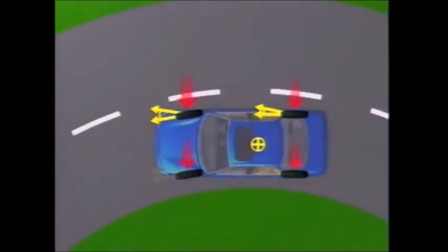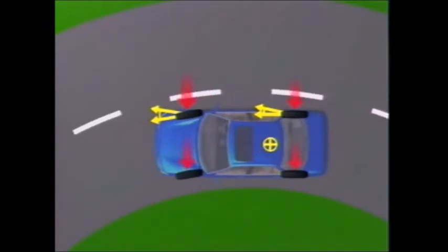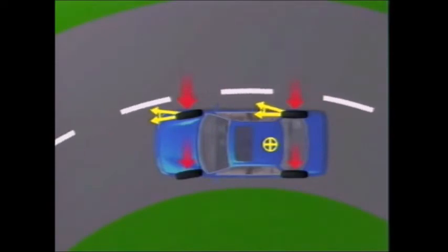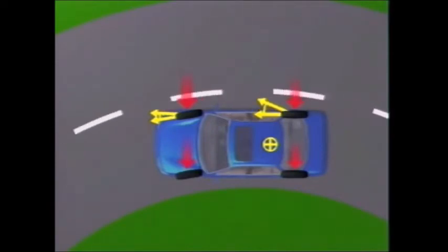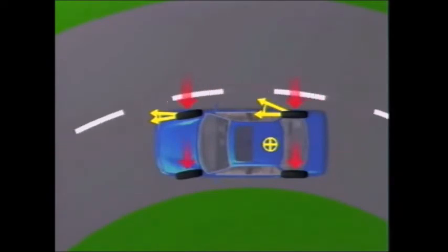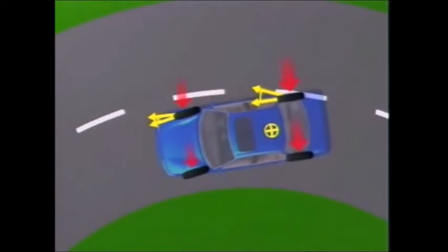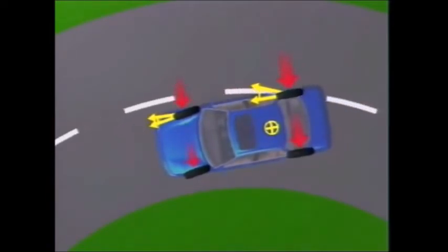With the centre of gravity closer to the rear, tyres carry more of the weight, so they operate at a greater slip angle than the front tyres. Larger side forces act on the rear tyres, which causes greater tyre distortion. This condition of higher slip angles at the rear causes oversteer.